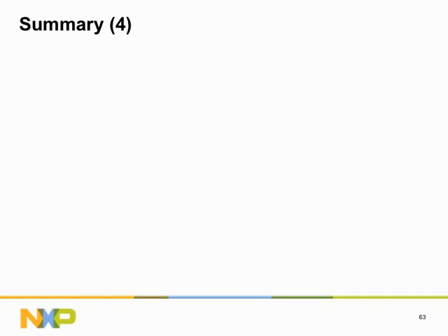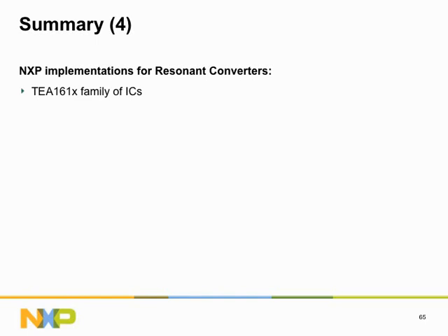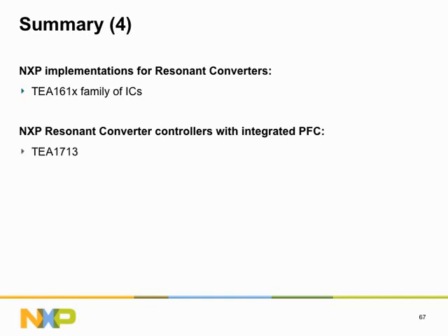And finally, we have dealt with resonant converters. The NXP implementation for LLC resonant converter controllers is the TEA161X family. A special LLC resonant converter IC is TEA1713, which has a boost mode PFC controller stage built in.